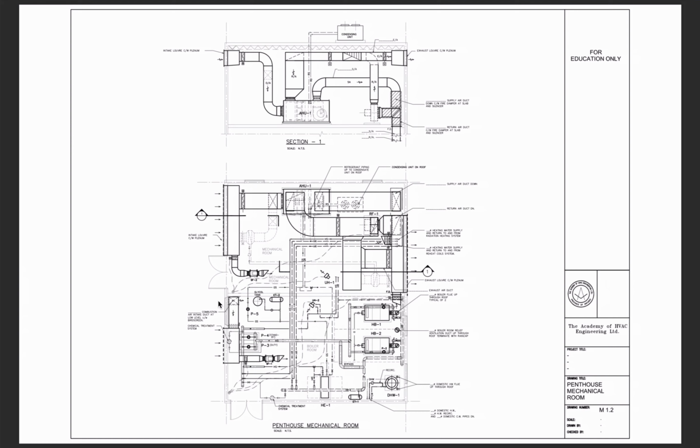Here's the mechanical room floor plan and elevation. As you can see, it includes the air handling unit that serves the main area. There is a supply duct going down to the main floor. There is an outdoor air intake. Everything is sized and selected based on your computations. The floor plan includes the air handling unit, the boilers, and all piping and pumps.